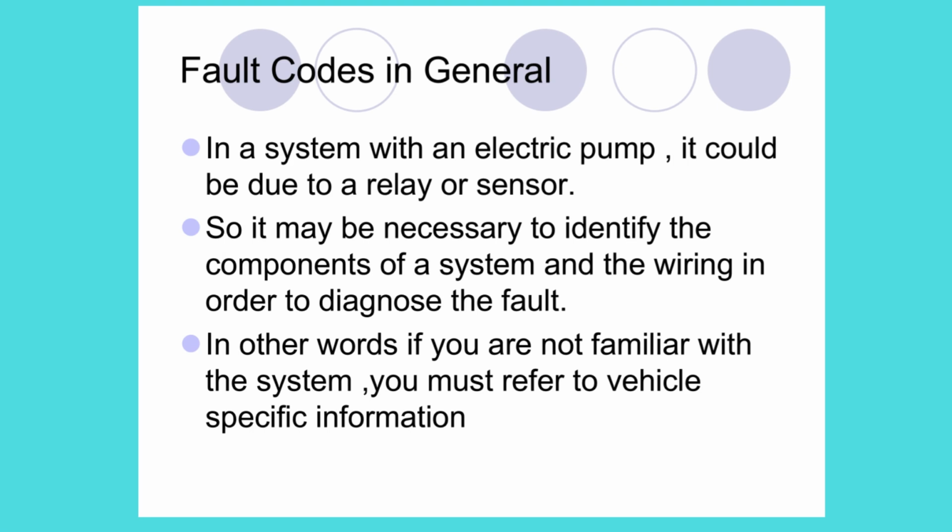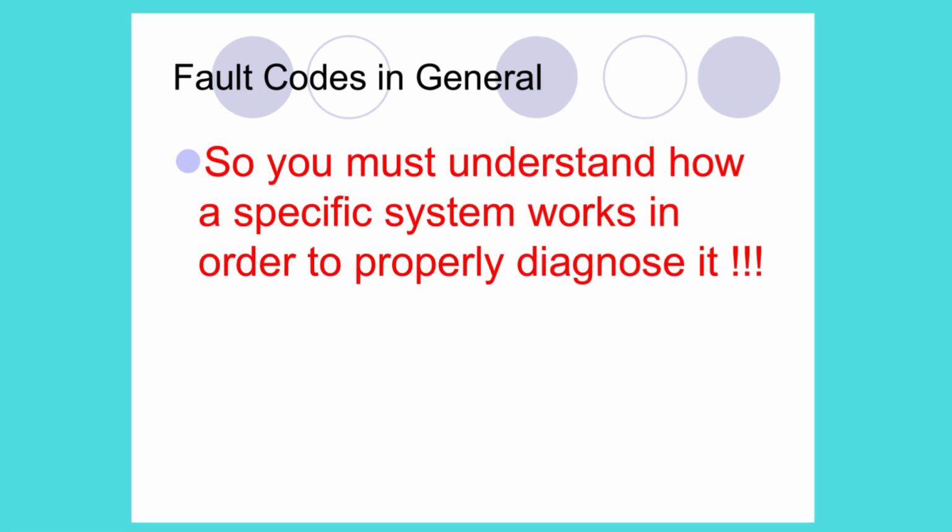So it is necessary to identify the components of a system and the wiring in order to diagnose the fault. In other words, if you're not familiar with the system, you must refer to vehicle-specific information, like workshop manuals. So, you must understand how a specific system works in order to properly diagnose it.